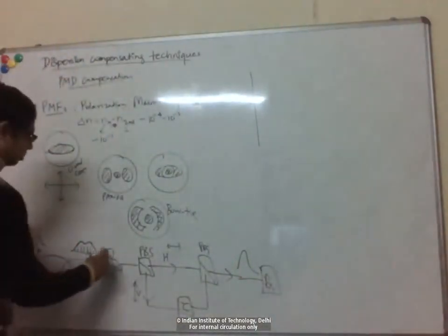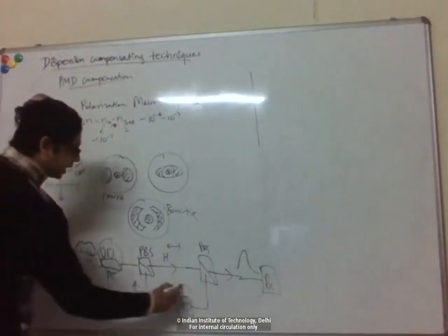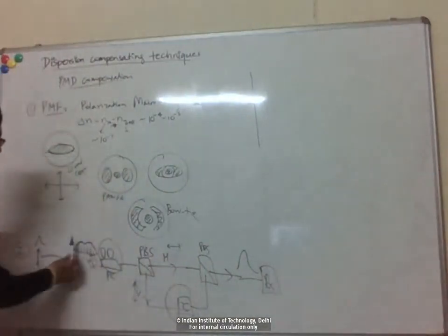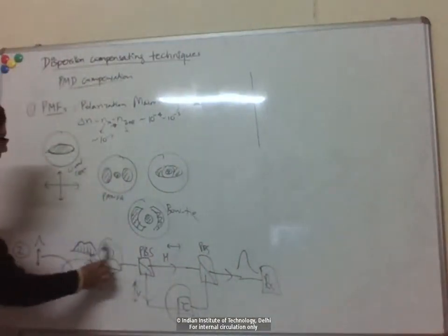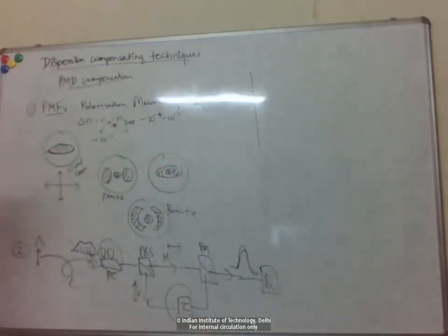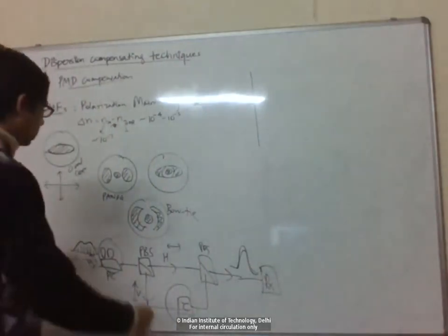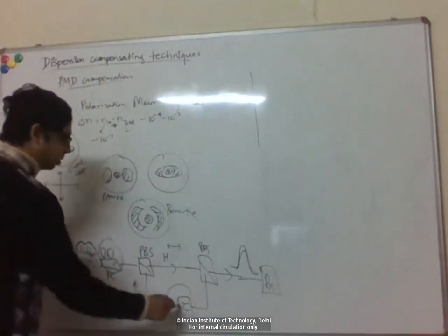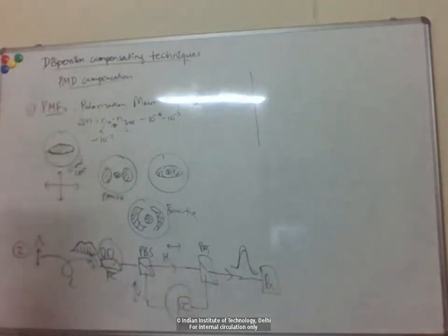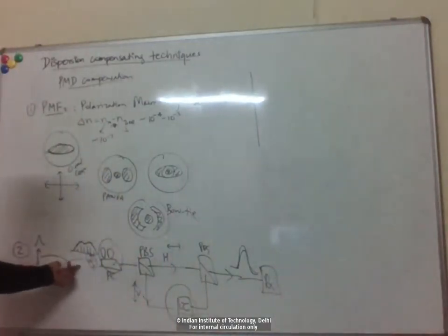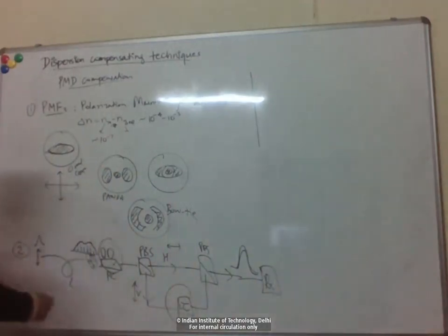So by playing with this polarization controller setting and this time delay, you adaptively control these two such that you compensate for the delays of the different polarizations and bring them back together. Okay. So this is an optical technique, but this needs to be updated in real time, both the setting of this polarization controller and the delay, to take care of the different stresses randomly happening here in the fiber. Okay, so this is an optical technique.